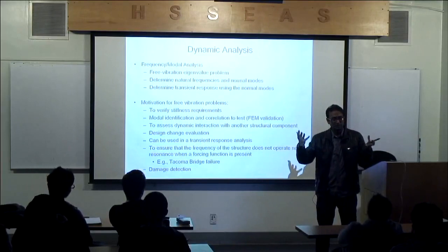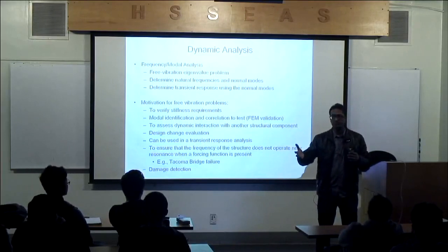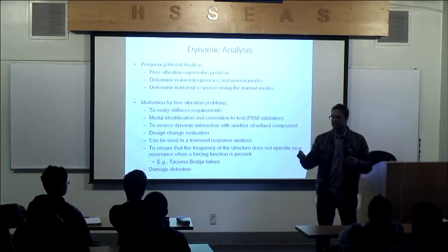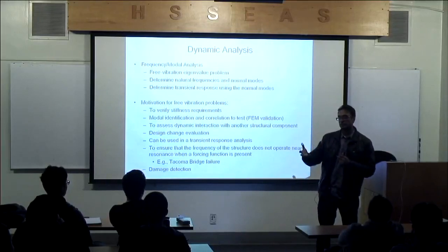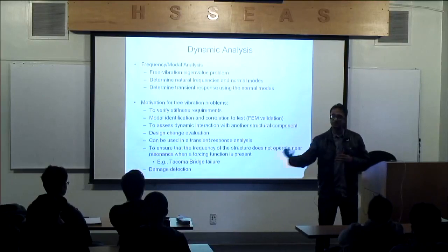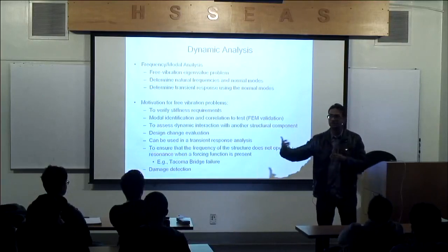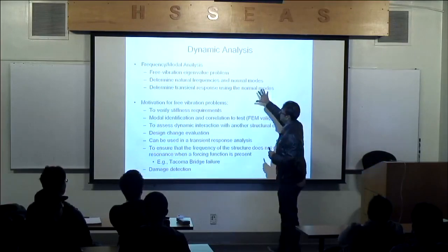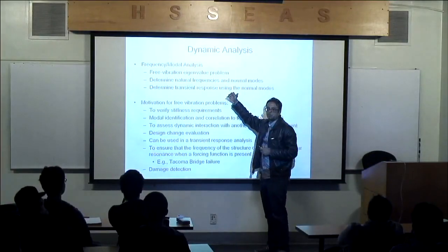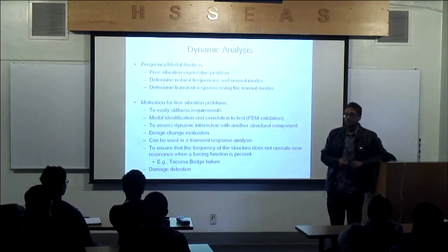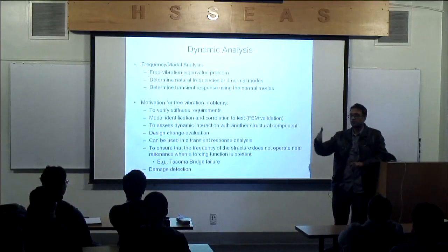Does that make sense to you? Like if I damage a beam, doesn't its stiffness get reduced? So if that shows us a stiffness reduction, perhaps I will see that in the mode shapes and the frequency information, and I can use that to determine, hey, there was indeed damage to that structure. So this free vibration dynamic characteristics problem that we'll be looking at today is fundamental to finite elements in many different ways and into real applications.